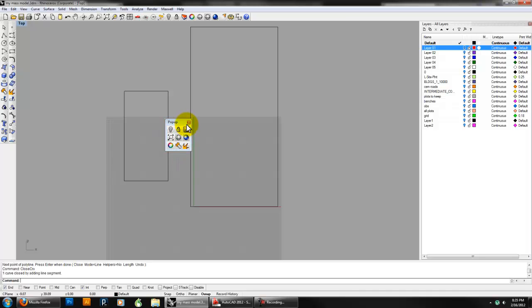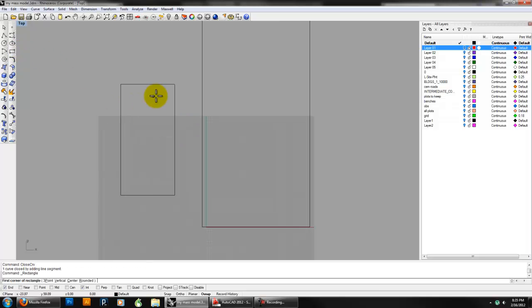I can also do the same technique I showed you guys in class. I could say explode. I could say offset, 25 foot. It gives me an offset. I could say offset, 15 foot. And then I can do things like trim, and then join these back together again.